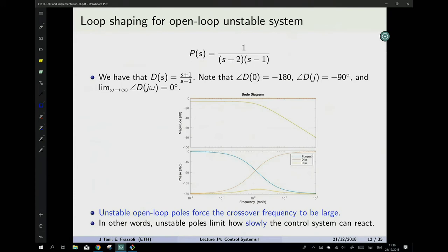So, in fact, one of the most common nuisances in control systems, which we'll cover in one of the first classes, is talking about adding some nonlinearities in the loop that actually makes sense. For example, the input has to be saturated. You must never allow the input to grow too much, because that either represents a very high cost or it's physically not the case in most situations. So to answer your question shortly, you never, ever, ever cancel out a non-minimum phase zero with an unstable pole. Okay, just a recipe for disaster.